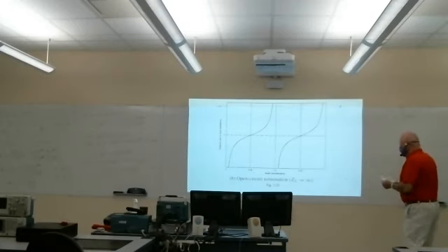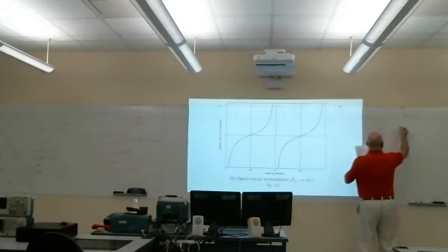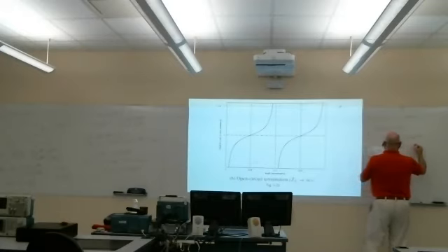So, again, with the short case, ZL equal to 0, Zn of L is plus j Z0 tangent of beta L, where Z0 is the square root of L prime over C prime, and beta is omega square root of L prime C prime.